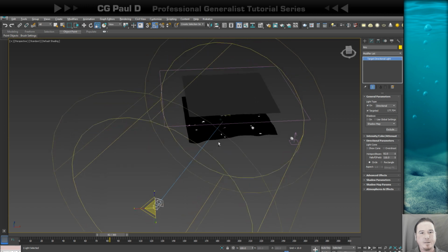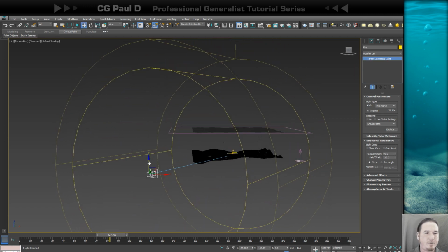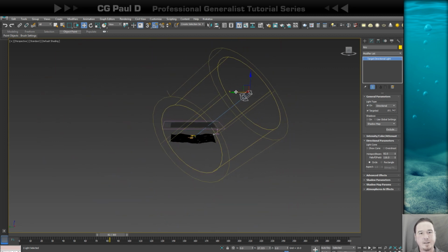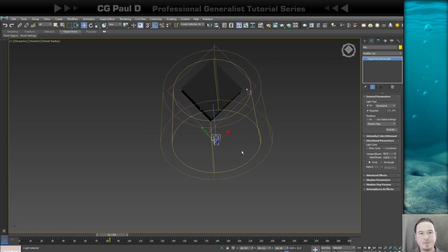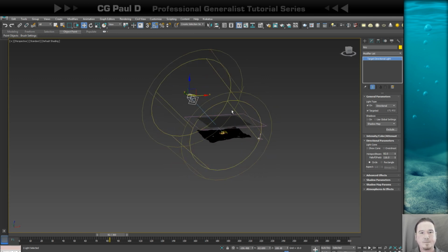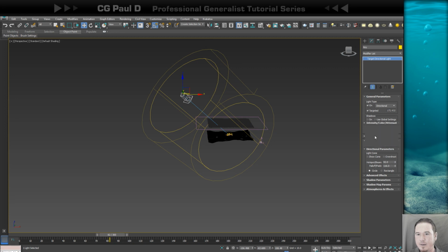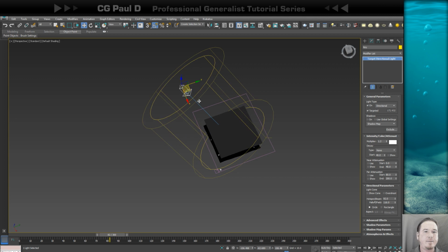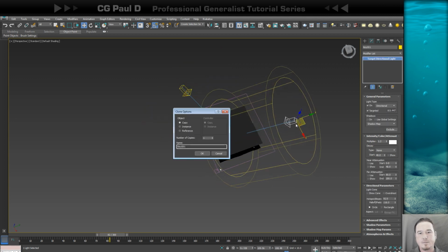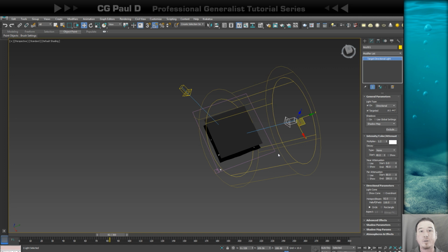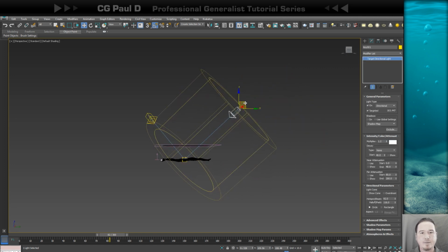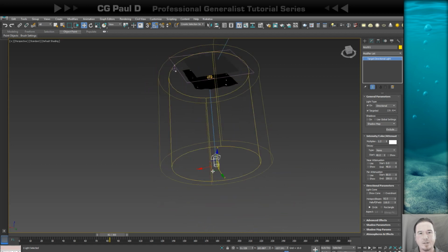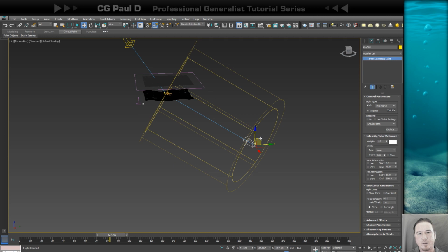Increase my cone a little bit, and just kind of standard 3-point lighting. This will be 2, but that's the idea, you kind of upper left off to the side a little bit. Intensity should be okay. We can bump it up a little bit, maybe 1.2. And then I'll go ahead and create a rim light, so we can kind of mimic how our material is behaving. Same kind of thing. And I'm just going to bring it down pretty far into the back area so we can create that nice little rim lighting.